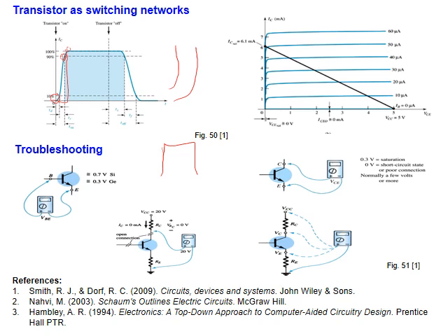Now, in the lab, how do we make sure that the transistor is working? Do you remember we mentioned before that we can represent the transistor by two diodes, either in these directions or in these directions, because of NPN and PNP. Since it is two diodes, we expect that from the 3 terminals only 2 of them will have a short circuit.